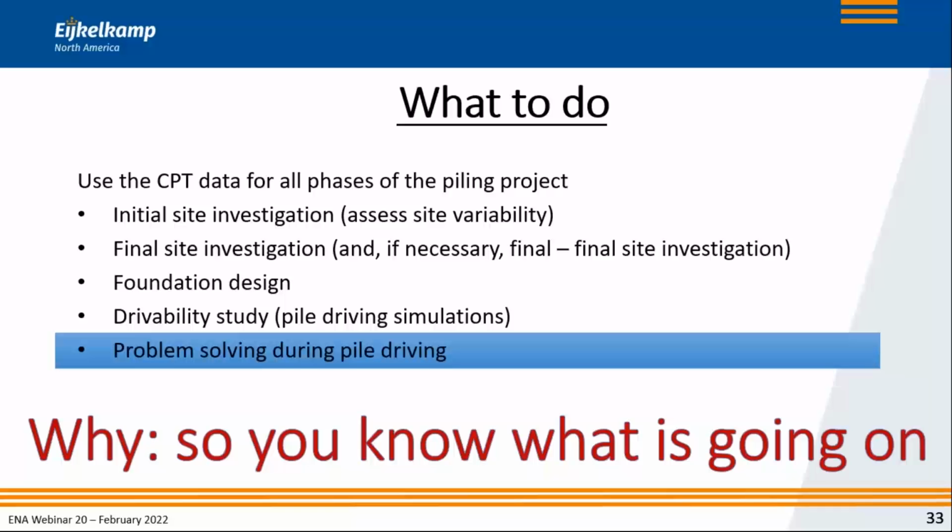You all know what it costs to have a pile driving contractor on standby, talking about, hey, what do you think? What would be the issue of this problem? What would be the cause of the problem? How can we resolve it? If you can just put an additional CPT cone in the ground, in 25 minutes you have a much better understanding of what's going on there, and in the end you might save a ton of money.